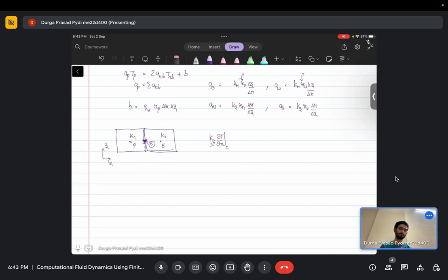Yeah, but how did we arrive at that harmonic mean? What is the rationale behind that? You use a distance factor F, which relates the distance between the cell centroids and the location of the face centroid. But the central idea there is your choice shouldn't affect your flux. Your flux should be the same.